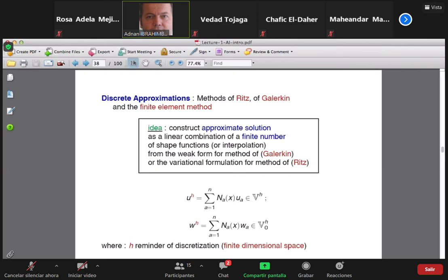As you choose these shape functions for the real displacement field, you also have to choose these shape functions for the virtual displacement field. And typically in the Galerkin method, the Ritz method that we discuss here, you choose the same shape function like this. Basically, that's the reason, because the problems, elasticity, heat transfer, are so-called elliptic problems. And the best thing you can do is basically choosing these shape functions to be exactly the same. That really preserves the symmetry and so on and so forth.